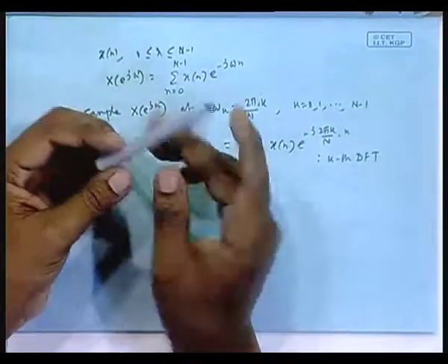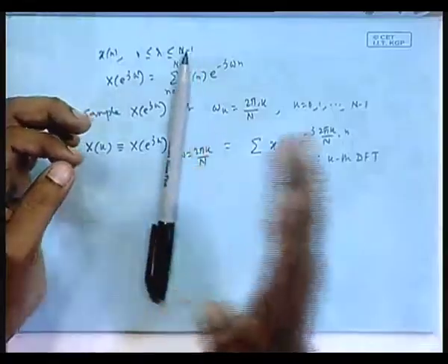In time domain sampling also, when you do this sampling, if you follow that non-aliasing condition of Nyquist, then the entire band limited function of time itself can be represented by its discrete samples, by its samples taken at 0, T, 2T, 3T, where T is the sampling period.